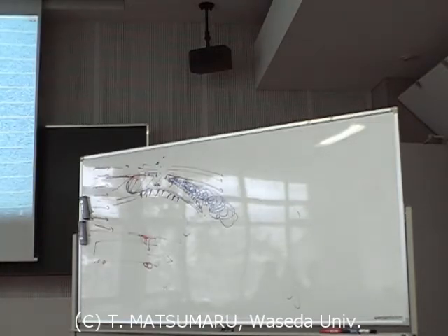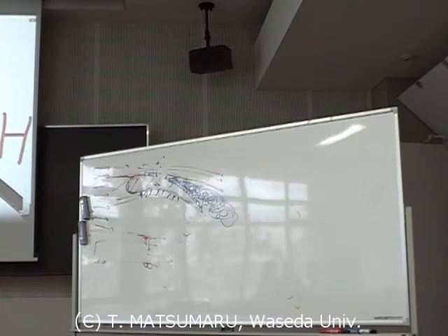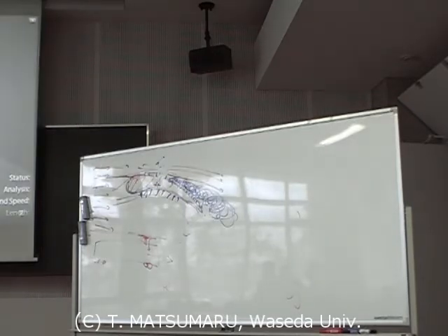With no friction, the air would conserve all of its energy from accelerating around the ball, and have just enough to leave the other side at the same speed that it started at. But since it has been slowed down by friction, the boundary layer doesn't have enough energy to push through. It slows down to a halt and then actually starts to go the other way at the surface. And right there, that is when the airflow separates, and that area of reversed flow is called a separation bubble, where air is recirculating and it has a lower pressure. And the difference in pressure between the high ram air pressure in front and the low pressure separation bubble in back causes a force known as pressure drag.